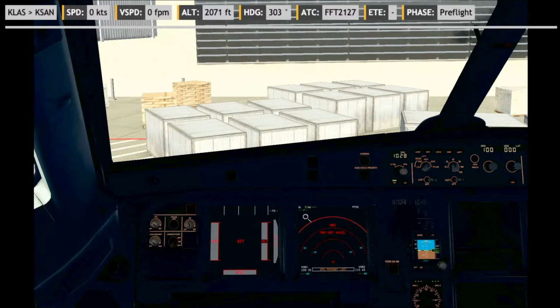So weather-wise, perfect weather for flying. Absolutely no issues except for our headwind. So to compensate, I brought 45 minutes of extra fuel on top of all of our legal minima, which is something I like to do, but now we have a really good reason to do that. Alright, and I would say that's our briefing done. I'm really happy with how this looks. We can get our airplane set up.